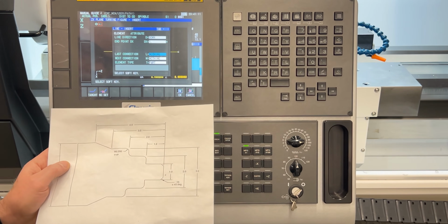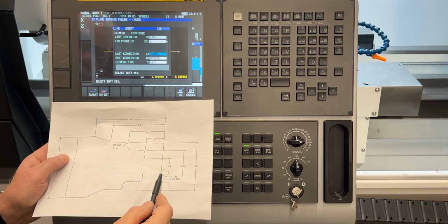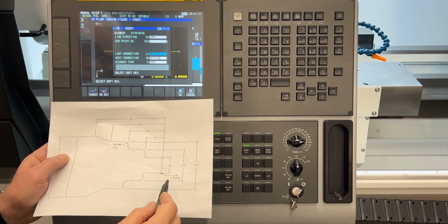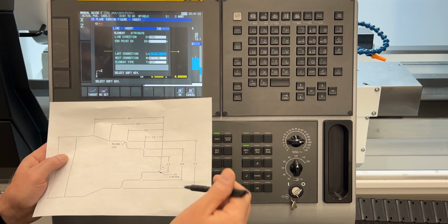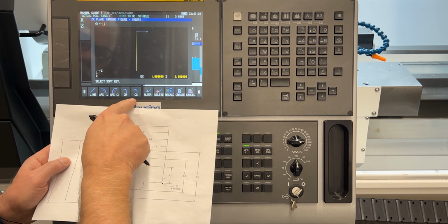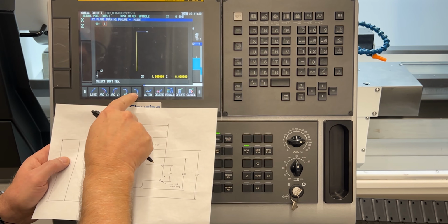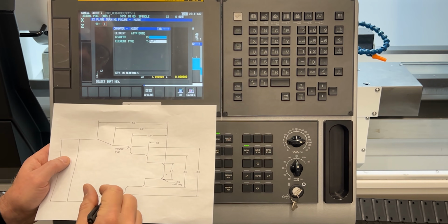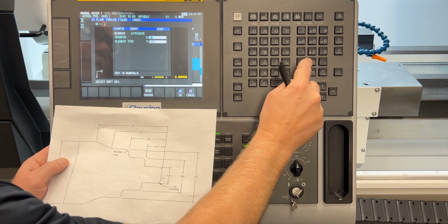And the reason I'm going to 1 inch is because I'm going to use an automatic chamfering icon that we have with this to blend that corner. And it only works at 45 degrees. So go down to 1 inch and say OK. So I have that there, and I'm going to do the CC, the chamfer the corner, and once that comes up, I'm going to put in there 150 thousandths.